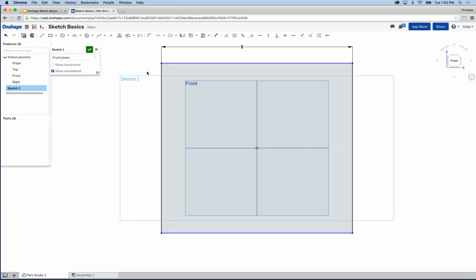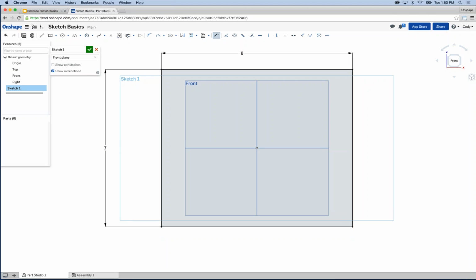Right? And if you ever have a scenario where it's underdefined, you can make a change and not be aware of how it impacts other things. If it's fully defined, the user is forced to delete something if they really want to change your sketch. So it's much more intentional. So again, our sketch goal here is to fully define it. So we'll add one more dimension. Okay, left click. This time we'll add a value of 7. And now notice the entire rectangle is black. So the entire rectangle is fully defined.